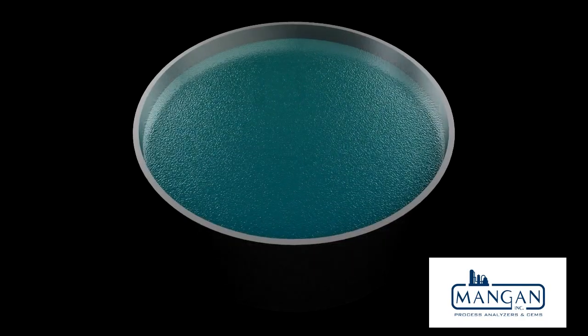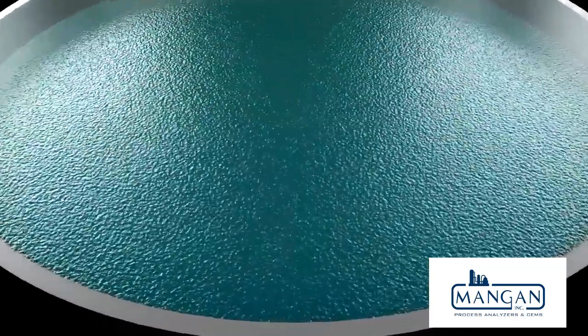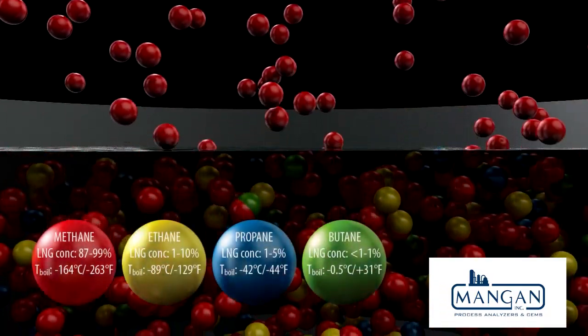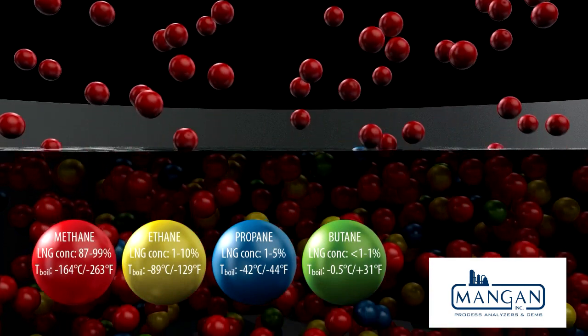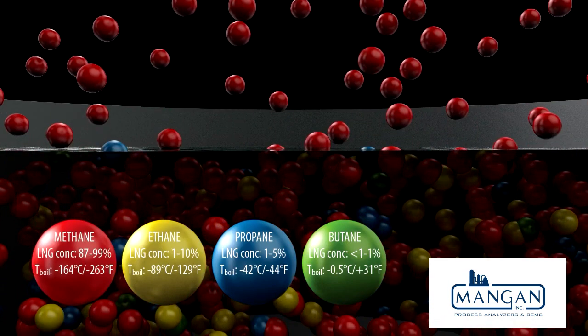Typically, the heating value and other properties of LNG are measured by gas chromatography to the well-known industry standards for natural gas. This requires a sample of the LNG, a mixture of cryogenically liquefied hydrocarbon gases with vastly different boiling points, to be vaporized without changing the relative concentration of the constituent components in the vaporization process. To stop component separation during vaporization in this type of fluid is practically impossible.